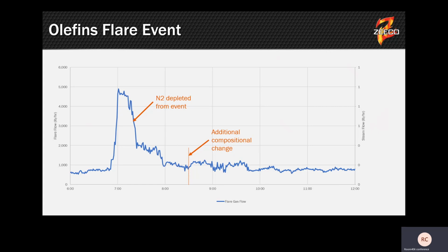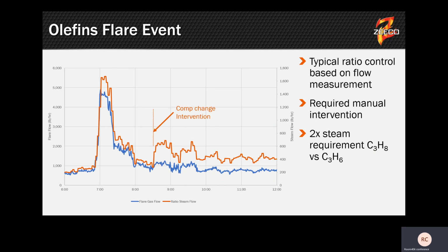There are some qualities about this incursion that I want to talk about. The incursion was an olefins and nitrogen release. So you've got some things that like to smoke, and you have some things that the nitrogen needs no smoke mitigation. And as that initial flow was curtailed, eventually the olefins kind of bled out of that system, and we got back to just a natural gas purge, which is really, really common. So we have two really important process changes that occur in this single event.